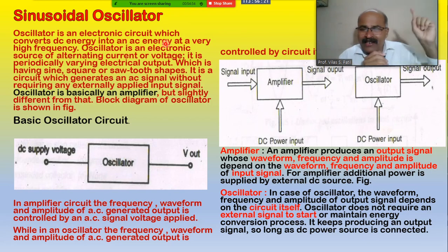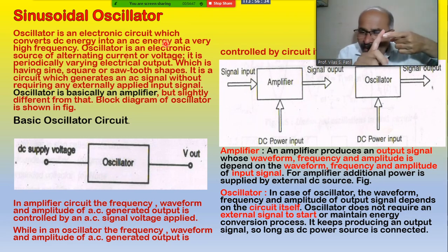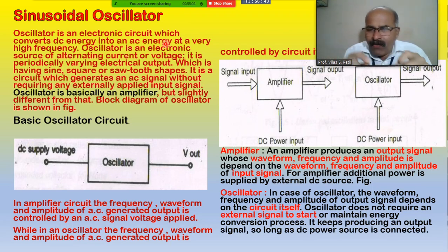We know that there is the rectifier circuit, which is the application of the diode. There are three types of rectifier: half wave rectifier, second is the full wave rectifier, and third one is the bridge rectifier. In half wave rectifier, only one diode is used to rectify the given input.